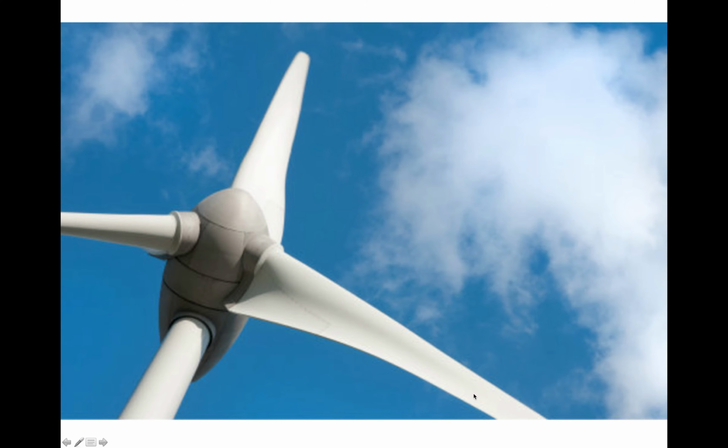Another feature of the blade is that there is a twist along the span of the blades. So it may not be obvious on this figure, right? But I can tell you there is a twist along the blades. So the pitch angle at different radius or along different sections of the blade is actually different. So there is a difference. Once we have understood the BEM theory, we can understand why the blades actually look like this.